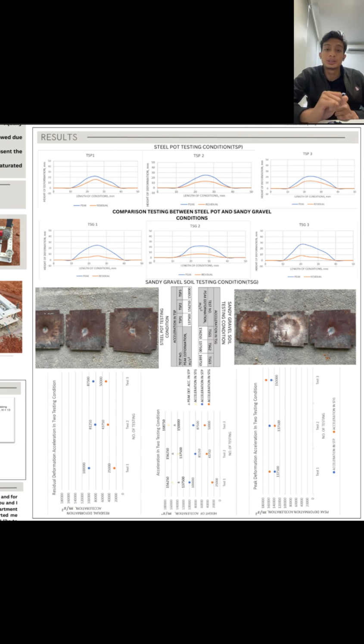So TSG2 is dropping 4% from TSG1 because of an error in setup. The density, compaction, and condition may influence the data. It is because the bolts are loosely attached. During the blast, the steel plate absorbs less of the impact because of the free space it has, and transfers more to the impact block. However, even though TSG2 has less peak deformation than the others, it still produces good and complete data.